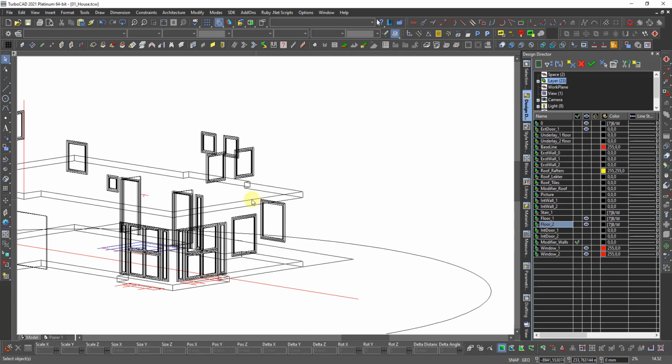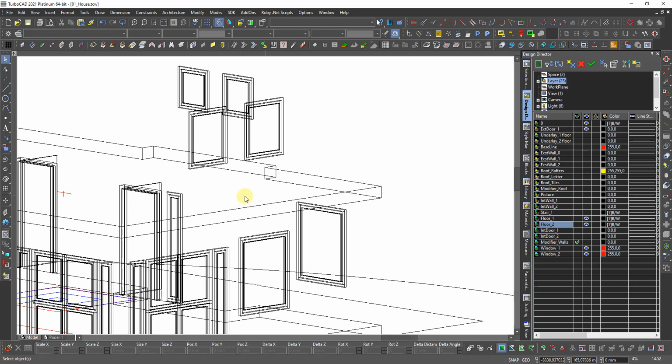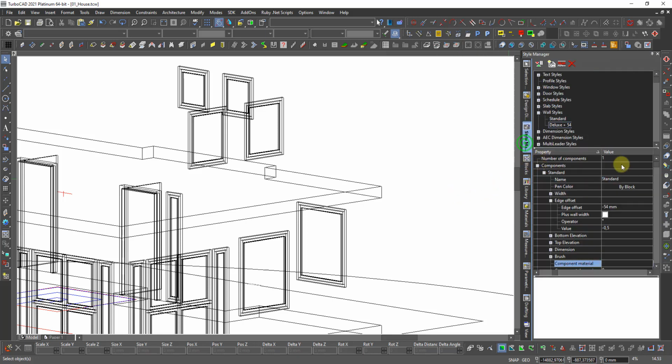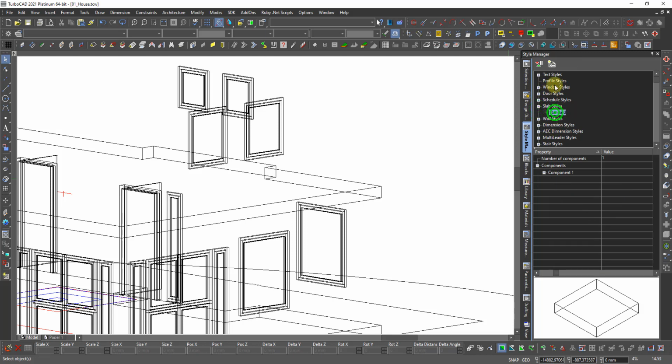This is just one thing. I want to have it show 2 layers, so I show the beam and this chipboard, I think. I call it chipboard on the top. There's a plate, the floor plate. So then I go into Style Manager and I go to floor, a slab. Take the standard, make a new one. And because this should be 198 plus 22, that is the name of the style.